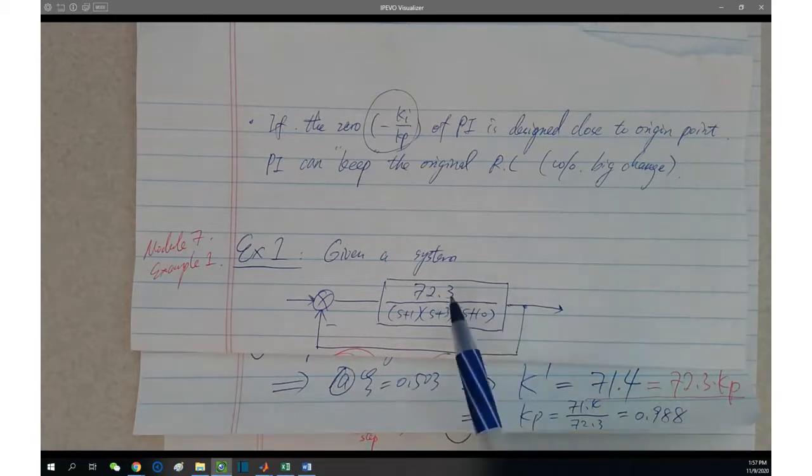Well, the reason is you don't know if this given system is good enough or not. Can you, by looking at this without sketching the root locus, know the damping ratio of this system? Oh, so this would be primarily to tell if it's unstable, right? Not only stability, but also the transient performance.